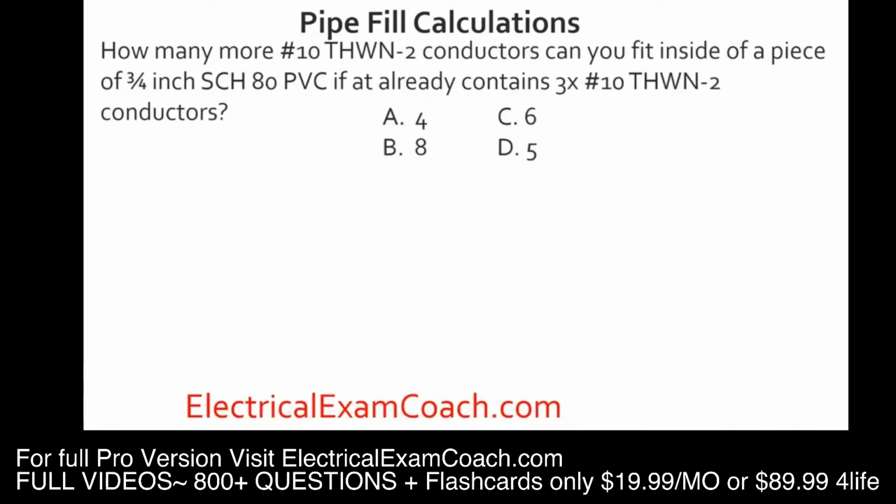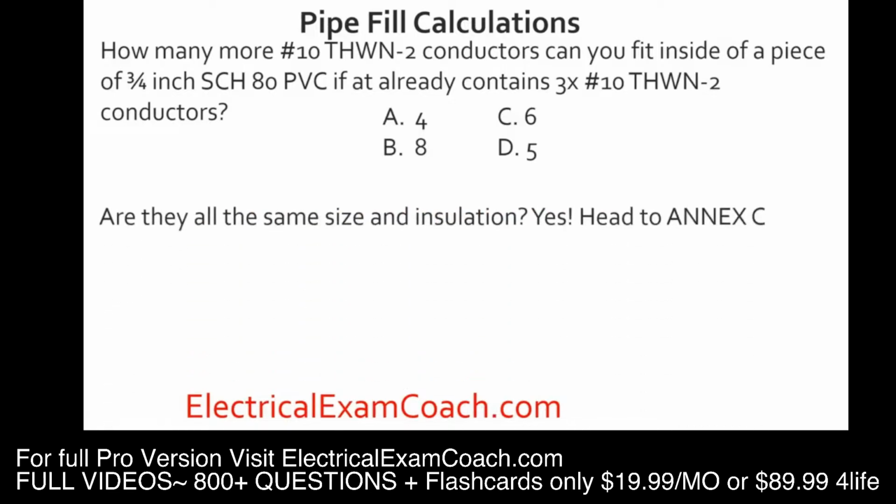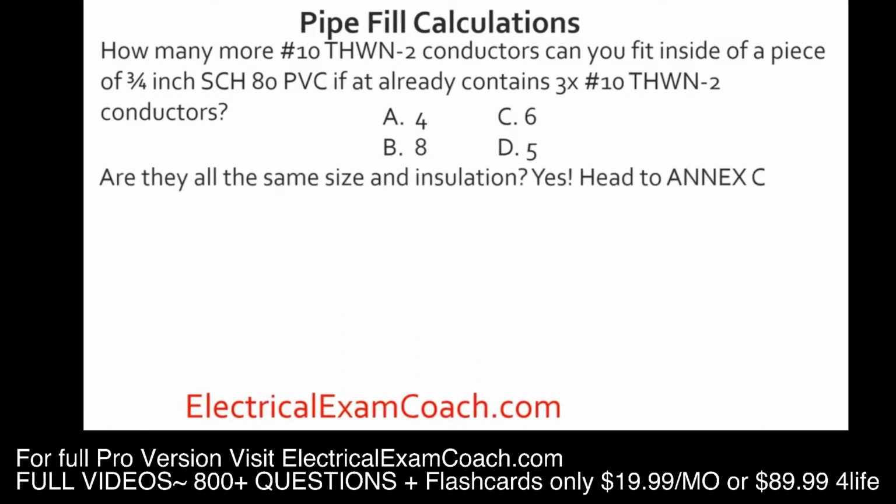How many more number 10 THWN-2 conductors can you fit inside of a piece of 3/4 inch Schedule 80 PVC that already contains 3 number 10 THWN-2 conductors? The first question we're going to ask ourselves: are they all of the same size and insulation type? They are, so we're going to head straight to Annex C.